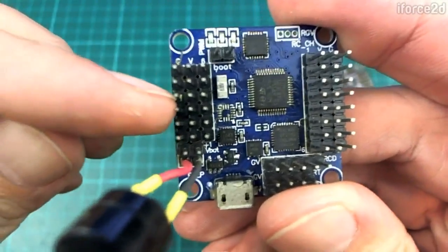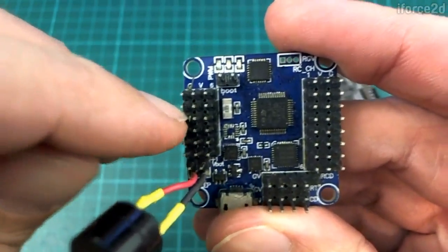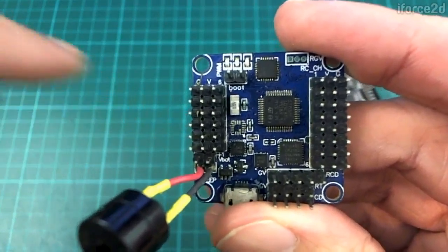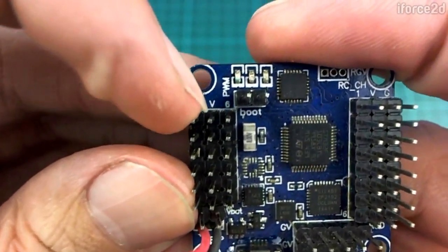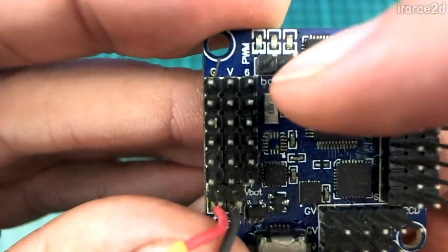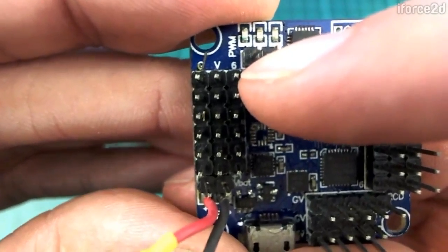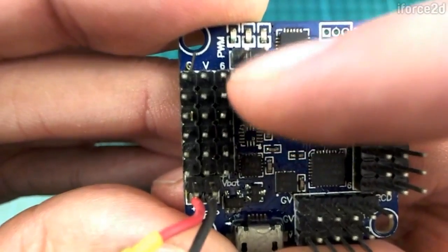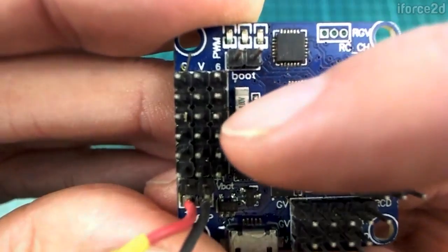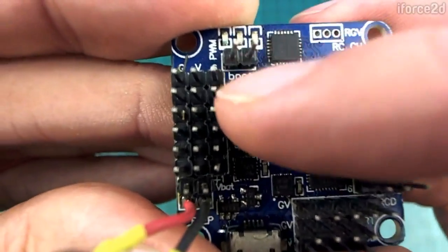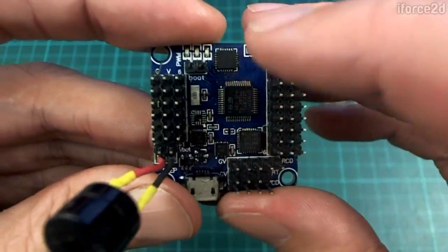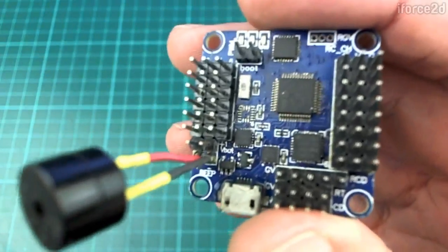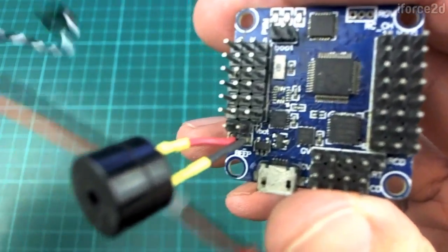Now over on this side we have the ESC connections, and this is outgoing information to the ESCs to turn the motors. But again, it's a very similar situation. We have a ground rail and then a positive voltage rail, and then the innermost row, which I shouldn't call a rail because they're not really connected to each other, is the signals going out to each individual ESC. And we have 6 of these, so this flight controller board could be used to make a hexacopter. But if we're just making a quadcopter, we're only going to use 4 of them.